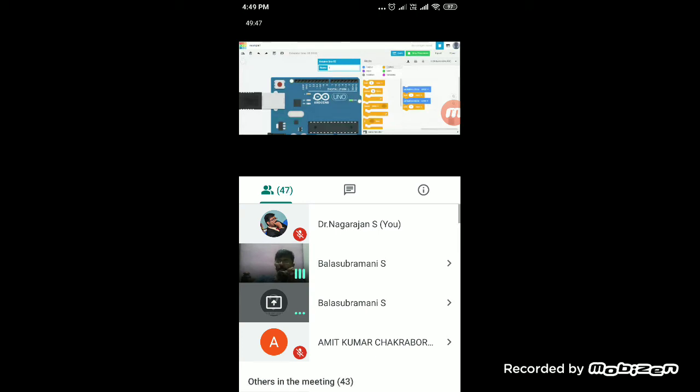Okay, now we are able to visualize it. My built-in LED is high for 1 second. This is how your Arduino processes commands in a sequential manner. First, set inbuilt LED to high, then wait for 1 second, so for 1 second my LED is switched on. Next I am giving the instruction to turn it off, so it is switched off for 1 second.